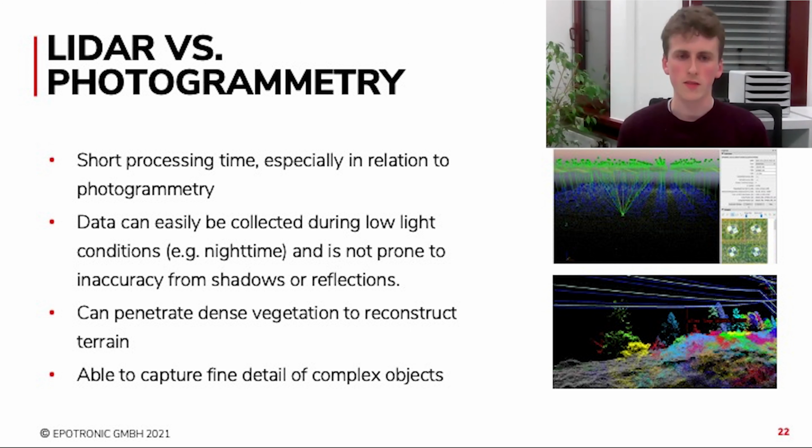Another big advantage is the conditions that LiDAR can be used in. It can be used in low light, including at night time. It's not at all affected by that, whereas photogrammetry is limited to good visibility and light, and photogrammetry as well is prone to shadows and reflections.